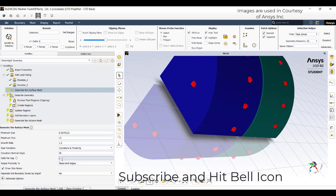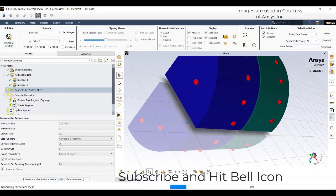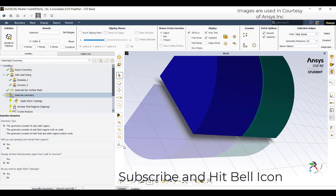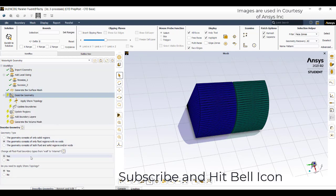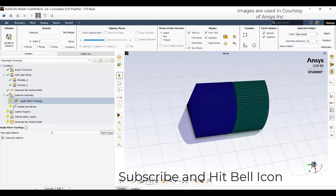And the remaining is the cells per unit gap. If any cells or any edges have proximity or are very close to each other, what is the number of elements that need to be formed there? That is given as cells per gap as 1. Right, so now we try to generate the surface mesh and we check how the mesh is. So the surface mesh will happen, and now after that we'll say if there are only fluids and walls to internal. So the fluid system between the two fluids will only be an internal region, not any wall.